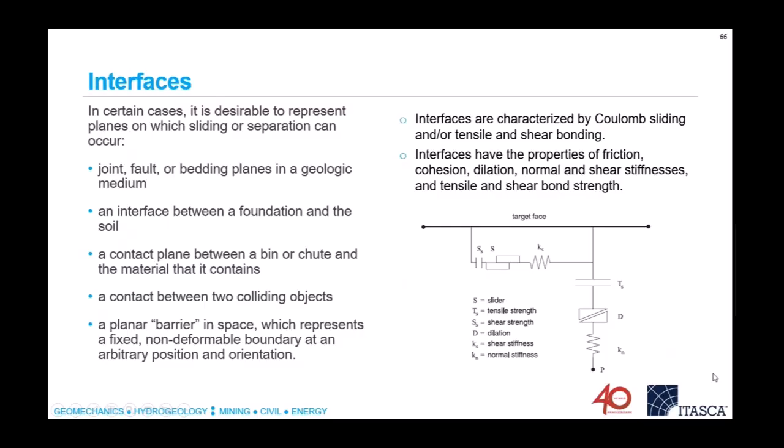A couple of words about interfaces. Remember, we have a continuous model, but we can split it into different disjoint blocks, and those blocks can slide in shear and basically exert shear along the interface, or even normal force, and they can even open and separate. So you use interfaces when you want to simulate joints, faults, bedding planes in a geologic medium, or any separation between materials.